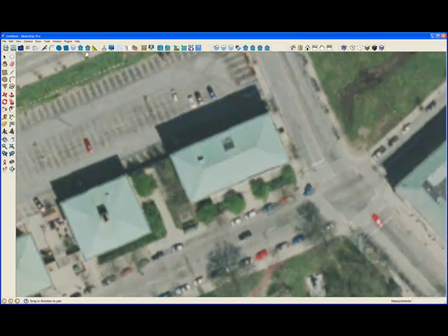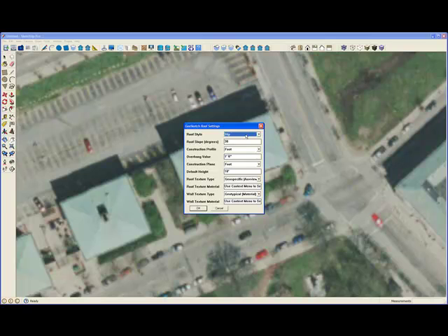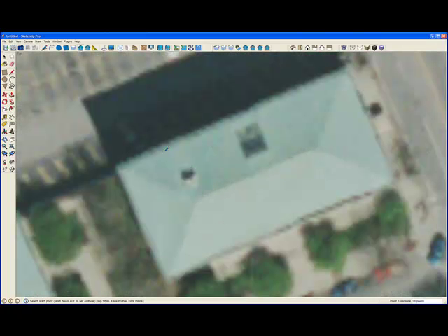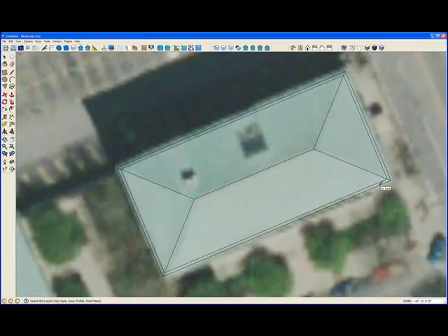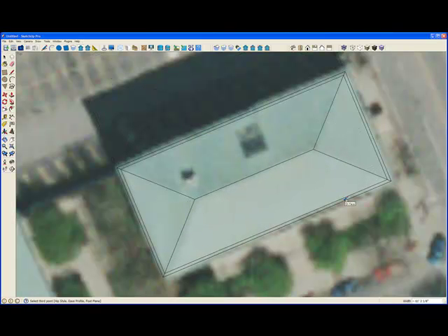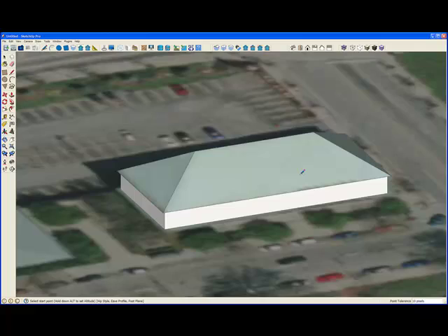In this case we'll build a hip roof, and I'll use this nadir selection. We'll select the choices that are typical for working from a nadir image, which is the eave profile and the foot plane, and we've got the hip style. So we'll use our tool and select the corners. And let me make sure that I had selected geospecific. Yeah, geospecific texturing, okay. And select that, and now we've got a geospecific textured building.